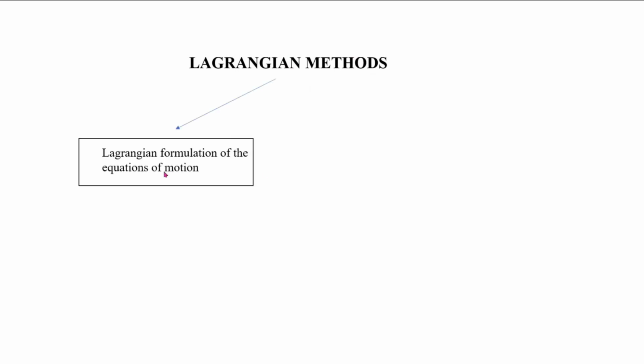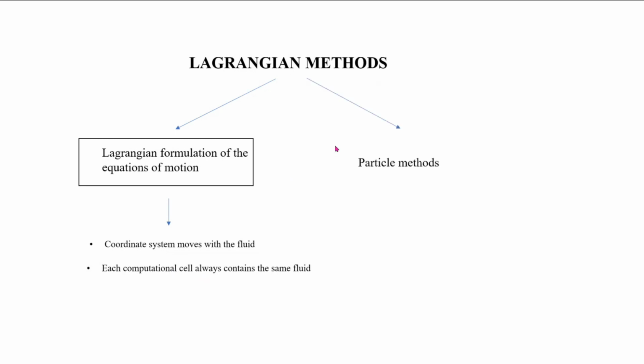Now let's look at Lagrangian methods. So we have a Lagrangian formulation of the field equations. The coordinate system moves with the fluid, and each computational cell always contains the same fluid. An alternative is particle methods. So I will discuss Lagrangian methods and particle methods.